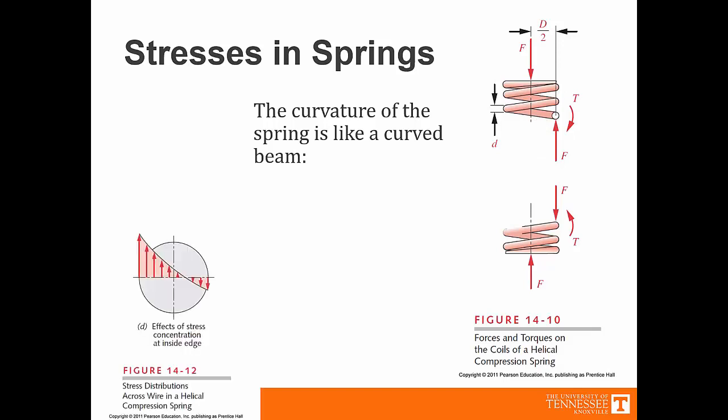I'm not teaching that in this class, but if you add that, you'll find that the curvature gives it a parabolic shape here. This curved effect is the total superposition of all other factors, and it also shows the effect that the spring is wound in a round orientation as opposed to a straight beam.